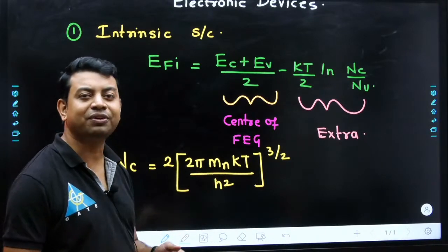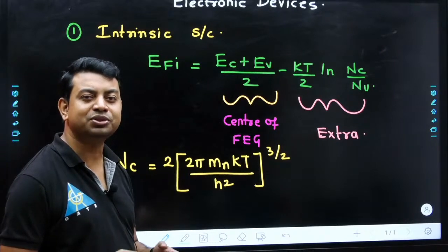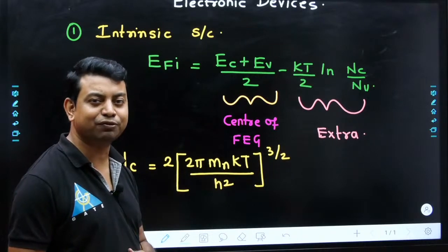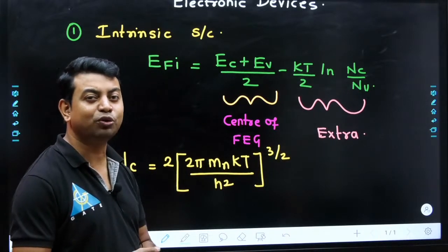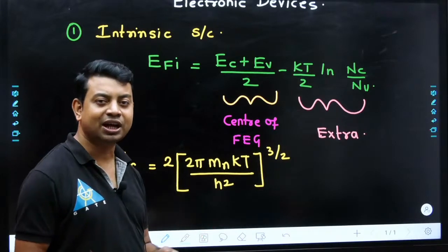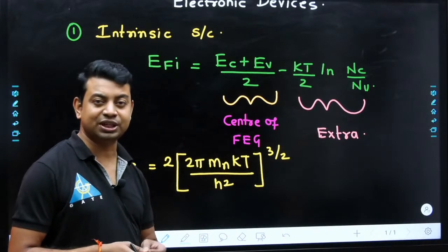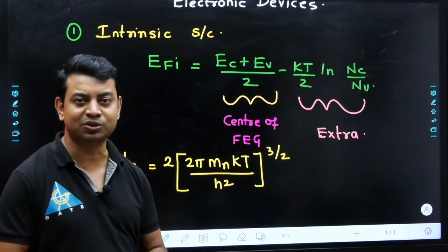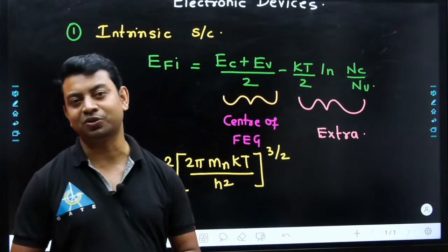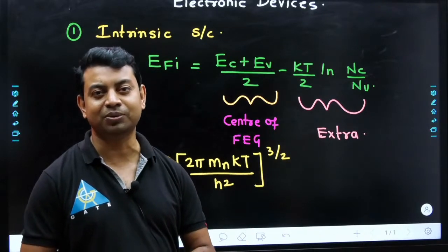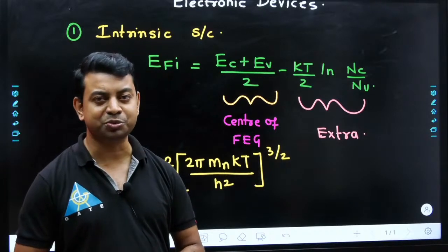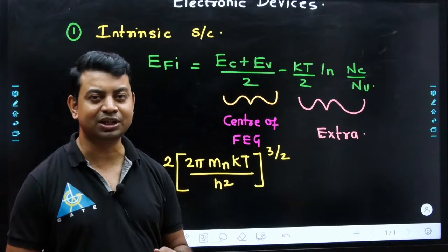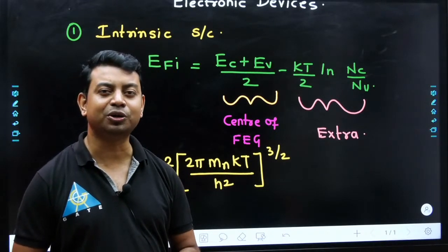These electrons get affected by the presence of different atoms in the neighborhood, because of which the electron is experiencing a force, and whenever the electron is experiencing a force, then definitely we are having effective mass. Those who are from the electronics branch have heard this word effective mass, and it is always compared with the normal mass of the electron, that is 9.1 into 10 to the power minus 31 kg. So whenever we are comparing, we take the ratio of this particular mass with the effective mass, and then we find out what the ratio will be.